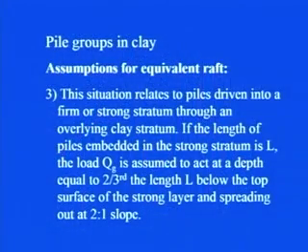The third point is that this situation relates to piles driven into a firm or strong stratum through an overlying clay stratum. The clay is lying above the firm strata, and in that case, if the length of pile embedded in the strong stratum is L, the load Qg is assumed to act at a depth equal to 2/3 of the length L below the top surface of the strong layer, spreading out at a 2:1 slope.